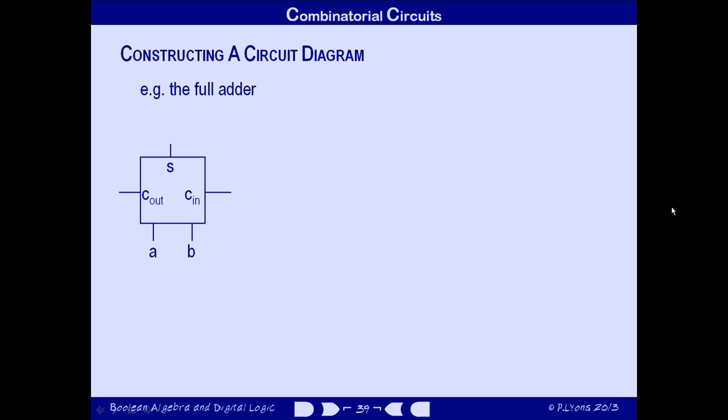What will it look like from the outside? I don't mean is it black or green or does it have hairy legs, but what inputs does it need to have? What outputs will it produce? And importantly, how does it connect to the other modules of the arithmetic unit? We already know that our bit slice module will have to handle two single-bit inputs, call them A and B, and a carry-in input, and it will produce a single-bit output called sum and a carry-out output.